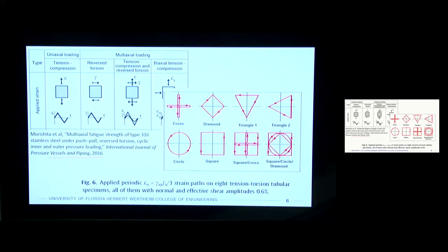So you can see at the left side here that strain versus time is just in the axial dimension. We know that. And then you could have multi-axial loading where in the second frame here, you have a shear strain versus time on the bottom, right? So that's going to be a rotational strain applied to the sample. And then when you put those together, I'll sort of circle this in light blue. When you put those loadings together, you have the combined tensile and torsion fatigue test.